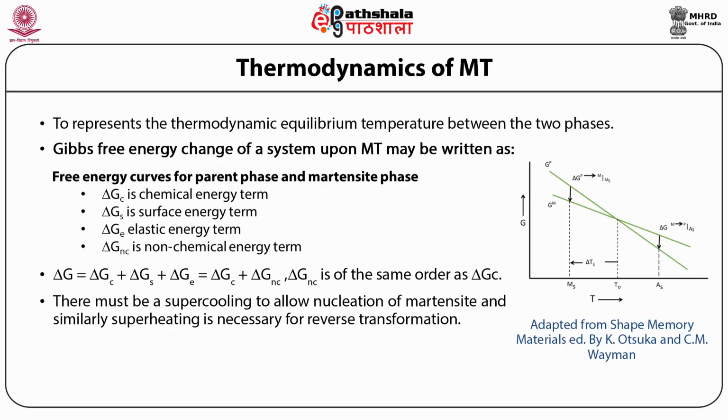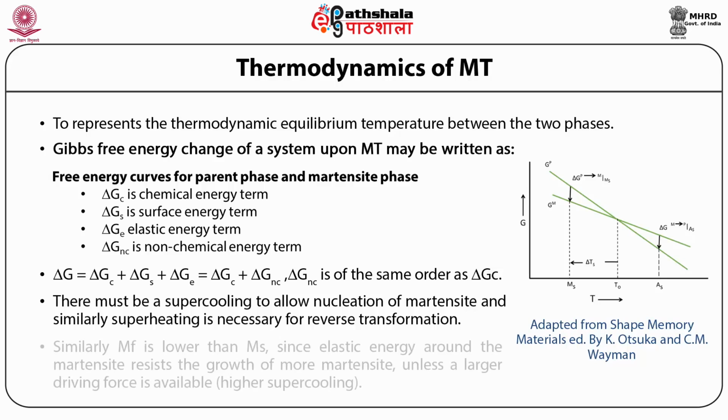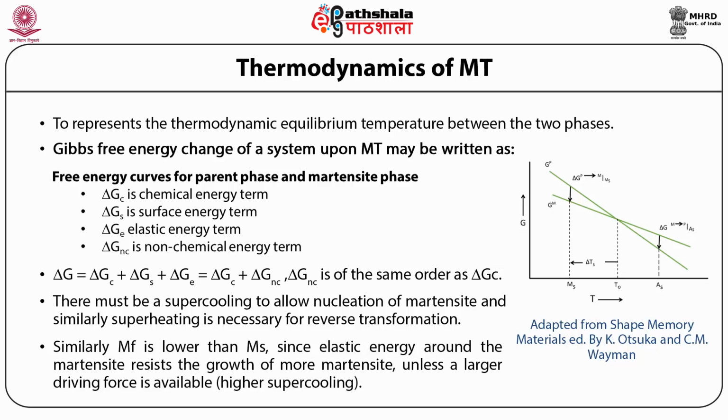Once the nucleation of Martensite phase takes place in the parent phase during cooling, it can grow only when the circumstances are right, meaning only when the driving force, that is the temperature difference, is larger than the elastic energy around the nucleated Martensite phase.